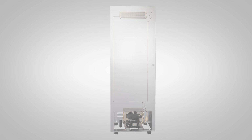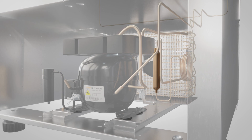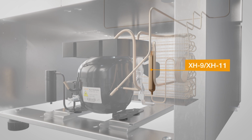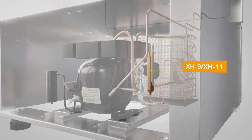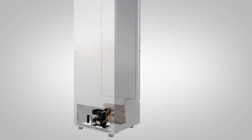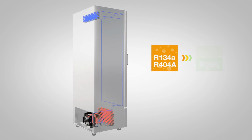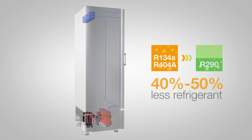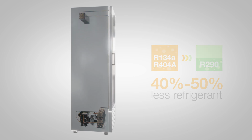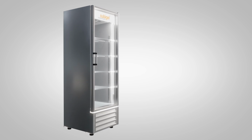When changing an HFC system to a propane one, it is recommended to change the filter dryer. For propane, it is recommended that an XH9 or XH11 filter is used. The amount of refrigerant always depends on the type of system and its components. Changing the system to the R290 means approximately 40 to 50% less refrigerant charge compared to the R404A. Furthermore, as it is a pure fluid, the refrigerant can be charged in liquid state or gaseous state.